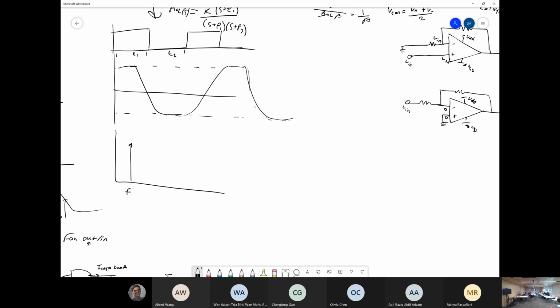Now, if you have a sine wave or a cosine wave, and we start to clip it symmetrically, eventually it's going to start looking square, right? Oh, this is not a very good example. But my point is that when you start clipping it, your edges are going to become vertical, and eventually you'll get a perfect square wave. If you clip a sine wave so much, because each up cycle and down cycle is the same amount of time and it's clipped by the same amount, your duty cycle will be 50%, same as a regular square wave.